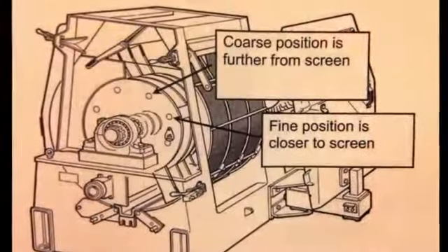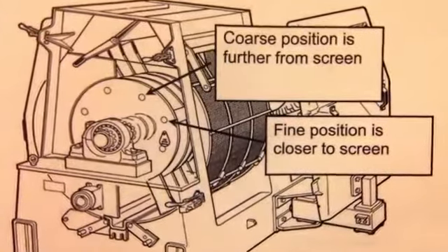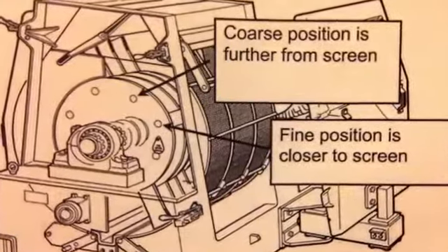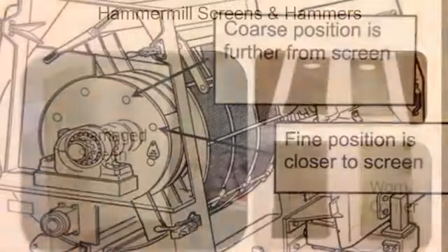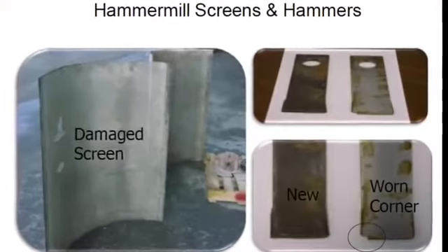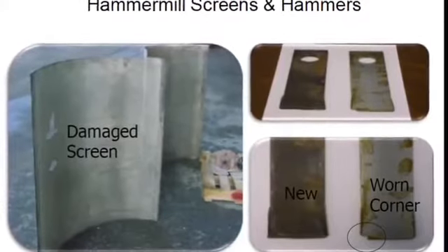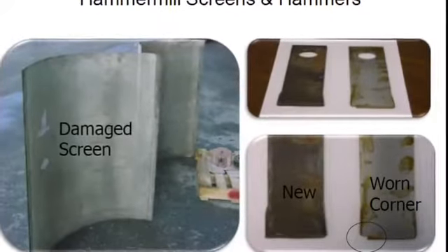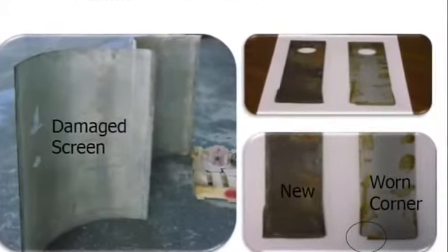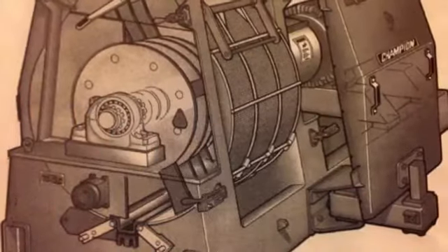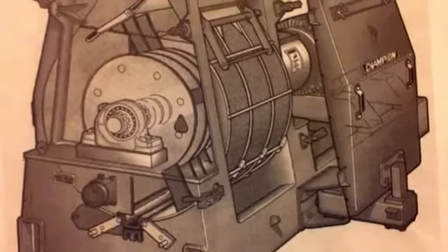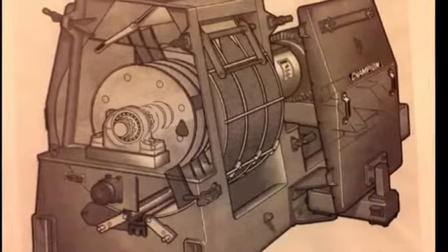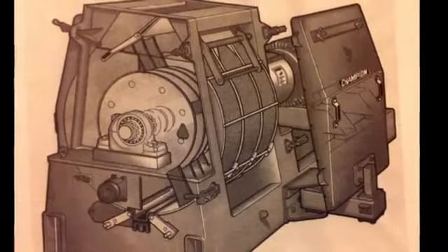Hammer mills are used in many processing facilities because of the ability to achieve a small particle size. The hammers and screens are relatively cheap to replace when they are worn down, and they are easy to work on when something needs to be replaced or repaired. Some of the disadvantages involve energy costs associated with running a hammer mill, and the particle sizes are not uniform.